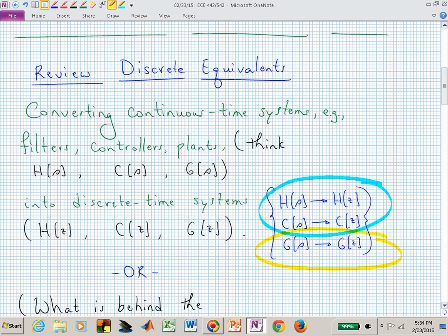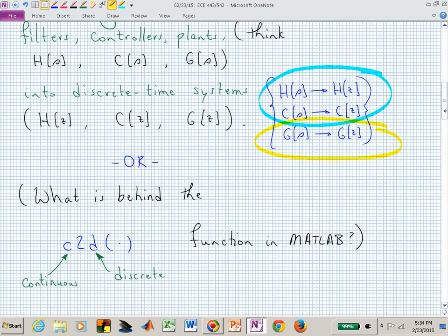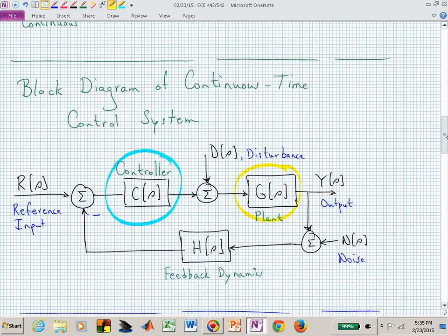I'm trying to indicate those 2 different scenarios so that now if somebody says, find a discrete equivalent, you're not just going to automatically say, oh, I'm going to give them the zero-order hold. You may not want to do that, and there are reasons for that, and hopefully that will be clear after today. You can generate most of these, if not all of them, in MATLAB with the c2d function, as we talked about last time.